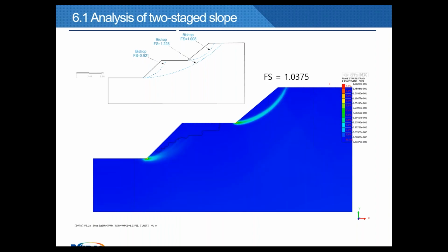One way is to put a higher parameter in some part of the model. So we can exclude this element from this one group and put it in another group, and give here, for example, cohesion 10 megapascals.